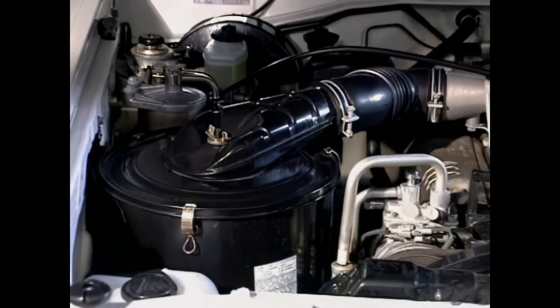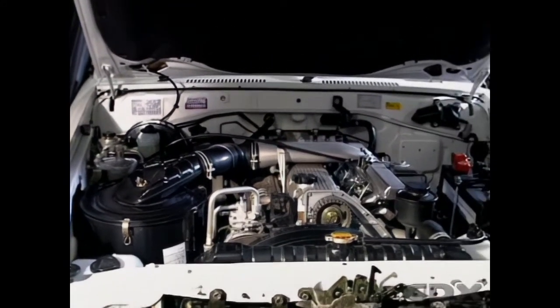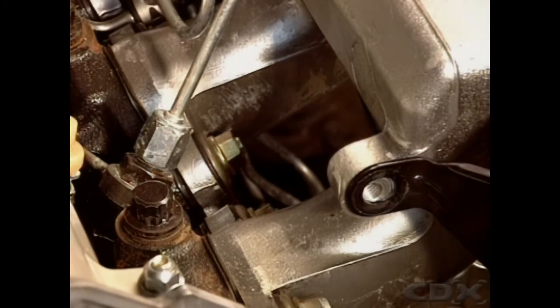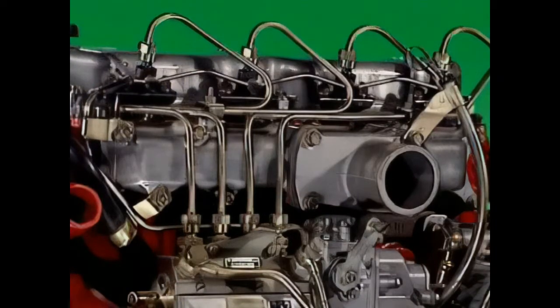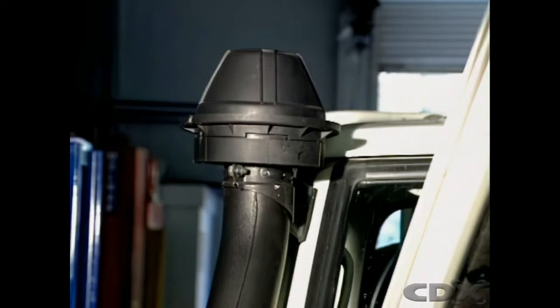The two main components of the intake system are the air cleaner and the intake manifold. But in a diesel engine, since fuel is delivered separately and the intake system carries air only, there's less restriction in the intake of the air than in a carburetted system. Also, since the diesel engine doesn't have a carburetor, it has no throttle plate. Some diesels use a pneumatic governor with a butterfly valve at the entrance to the inlet manifold. Diesel engines often have more than one air cleaner.